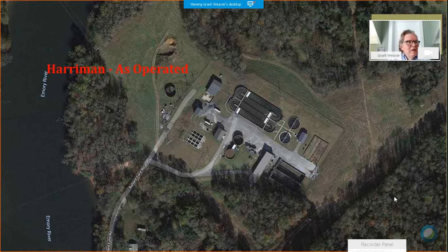So instead of running 4 rotors 24/7, they're running no rotors much of the time, and probably with almost as much benefit as when they have even just one rotor on. So a huge reduction in the amount of electricity used. What's that done? It's created a completely air-on environment when one of the rotors is on. The whole ditch goes aerobic, and then when the air is off, the whole ditch goes anaerobic.